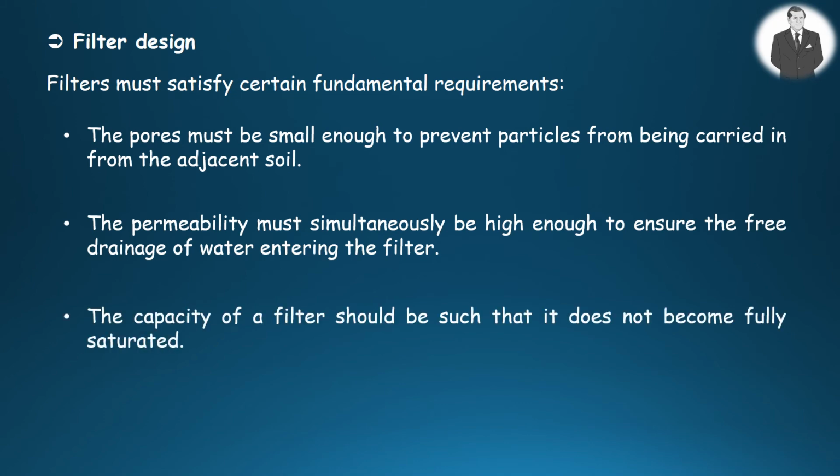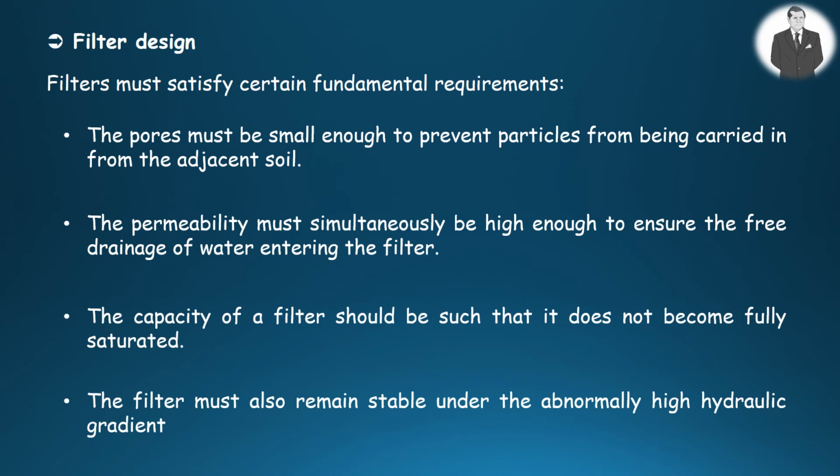The capacity of a filter should be so much so that it doesn't get fully saturated. In addition, the filter must stay stable under the unnaturally high hydraulic gradient.